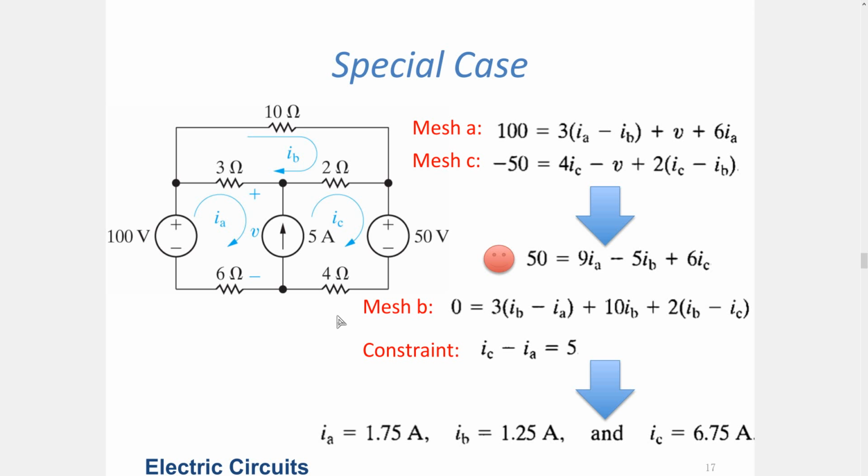As you can see, with the mesh currents, it's a bit of a harder task, because in practical life, in order to measure the current, you have to break the loop. That requires a surgery on circuit level. You have to desolder, disconnect the component, and put an ammeter in series with it, then make your measurements. It's a bit of a tedious job. Plus, mesh currents doesn't allow you to solve non-planar circuits, so that's a limitation.